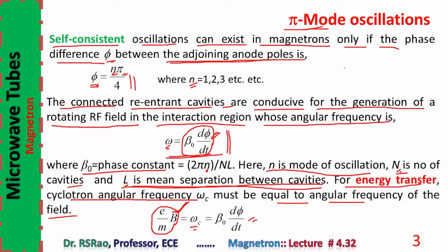This selection is through the selection of small n, capital L, capital B. Only that particular frequency component becomes capable of accepting energy from the electron bunches. It is then taken out of the device with the help of a current loop.